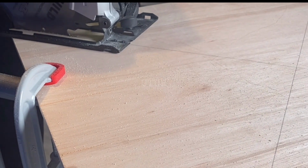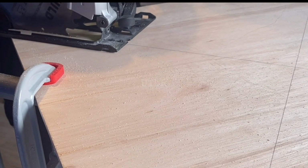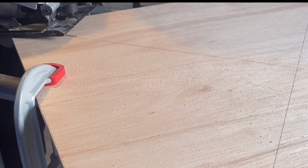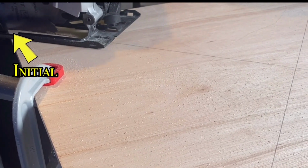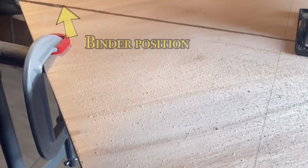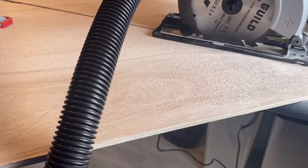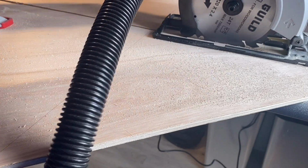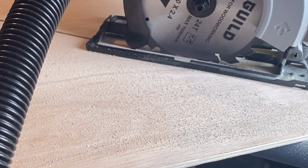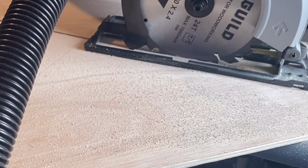After which, you can reposition the working tool along its line of travel, okay, ensuring that the blade doesn't rest on the wood and it's free spinning, whilst you're trying to retrace its line of travel. You can start at the very initial position where you started making your diagonal cuts, or you can start off at the position where the saw blade stalled, but if you're experiencing difficulties from the stalled position, you can start from the initial position and retrace your line of travel all the way through whilst making your diagonal cuts.